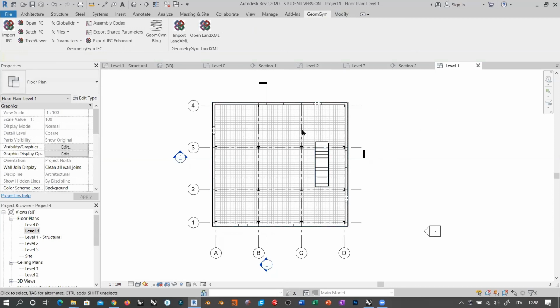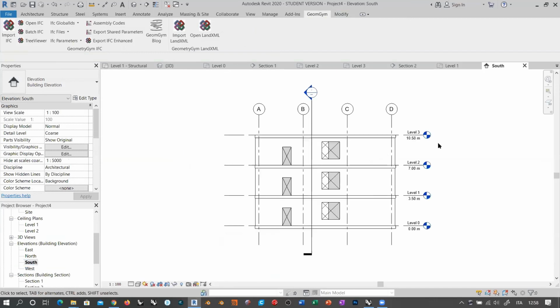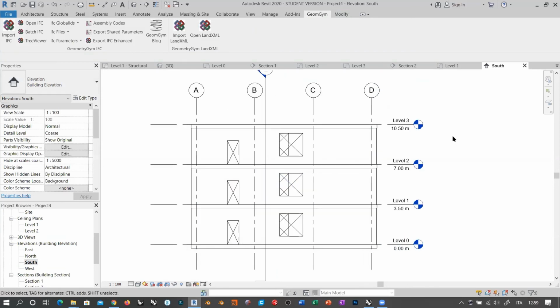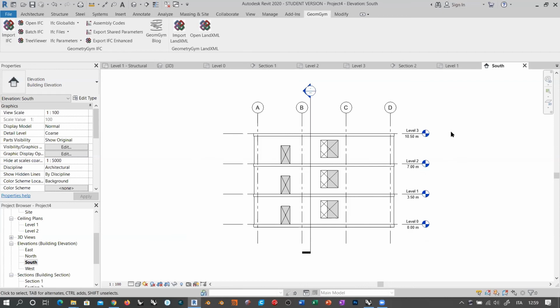Okay, so this means, for example, if we go back to the south viewport, you see that now we have this. Oh, my bad. I think in that case it's in to out for the walls. You see the bricks are on the inside of the walls. But anyway, we can simply fix this in Grasshopper by reversing the list of connected material layers. But everything is respected. You see the tweaks that we did, for example, by aligning the levels and so on,